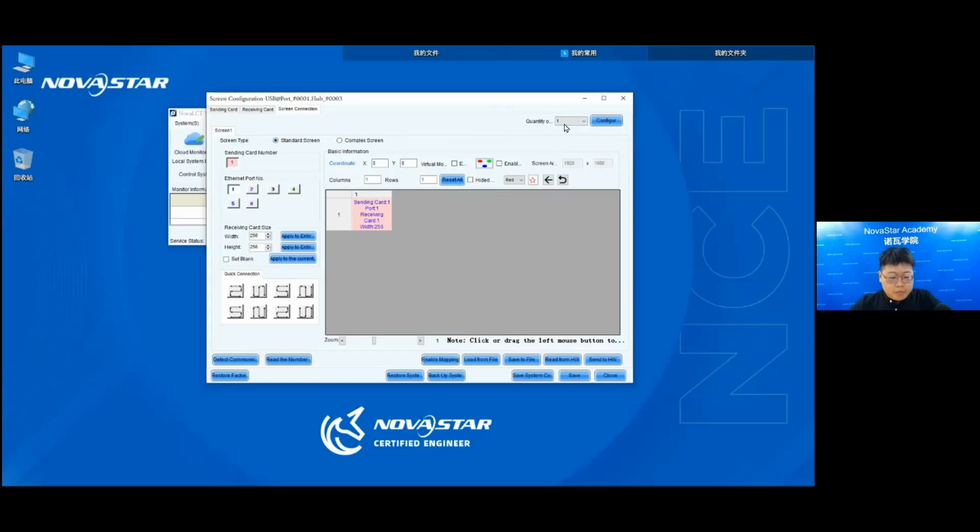We can see all of the ports of the sending card, because this sending card has 6 outputs. And this cabinet has 2 columns and 2 rows, we set it here, and we reset all. For each cabinet, I mean each receiving card, the size is 256 by 256. So we will set the cabinet size over here, and we choose port 1. The screen connection should be like this, I mean, the main channel. So we have done the screen configuration. Over here, we choose to send to hardware.